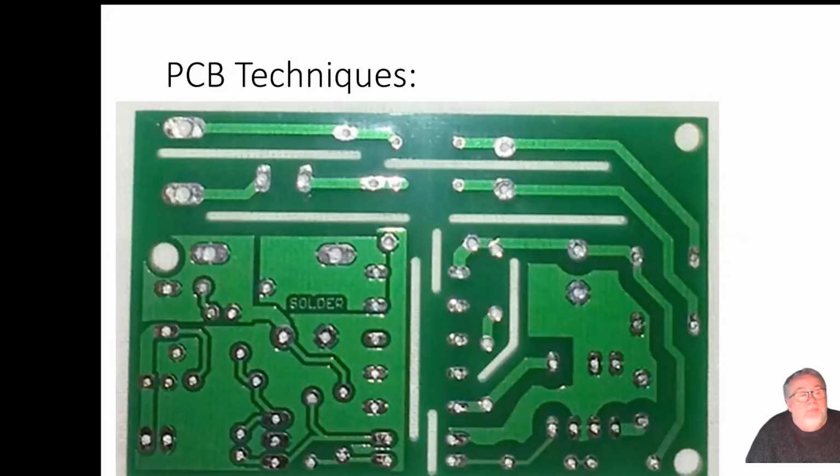If a printed circuit board gets a bit of moisture or a bit of humidity, its conductivity increases, its resistivity decreases, and you can get arcing between the tracks. So in order to stop that from happening, we put a slot. Air has got much better characteristics as a dielectric than printed circuit board material has. So it's better to have air than it is to have PCB material. So you'll find that there are those slots, first of all, between the mains wires.